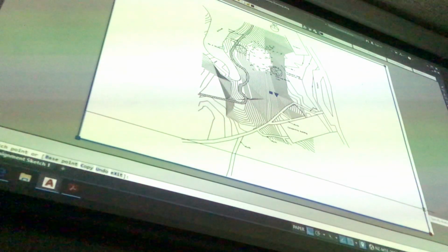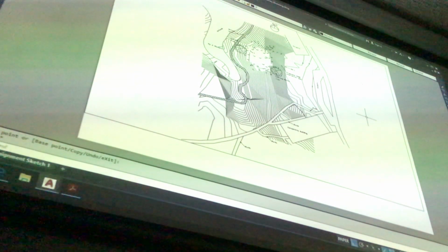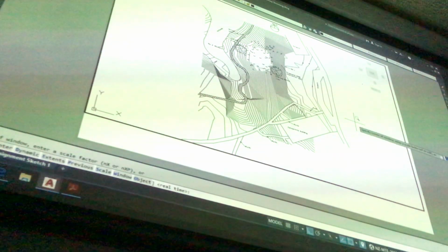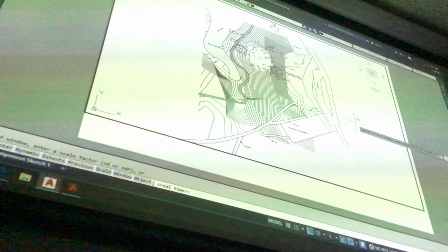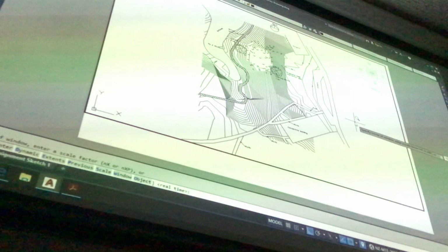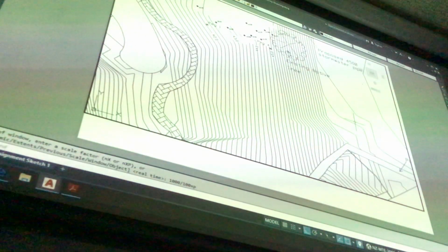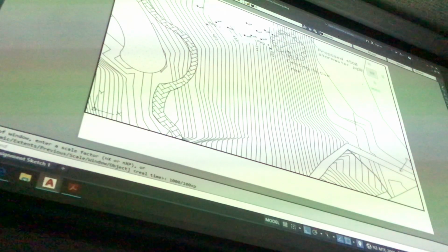I'm going to move this up a bit for my title block. Okay, just before I put my title block in, I need to get the scale right. The scale is 1 to 100. So I go inside the viewport, I go Z enter, 1000, oh, yes there is, /100 XP. Is that correct from last semester? Let's see what happens. Believe it or not, that's correct.